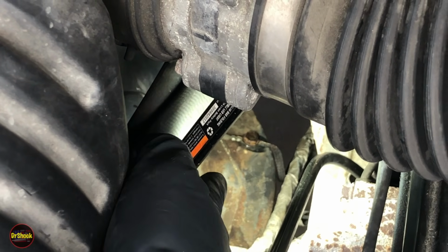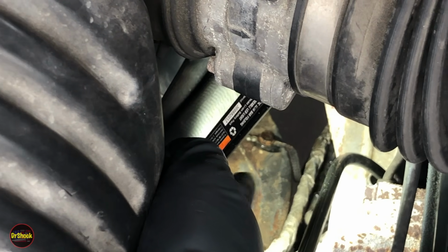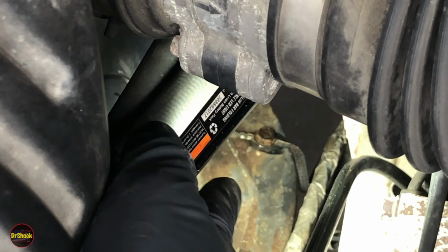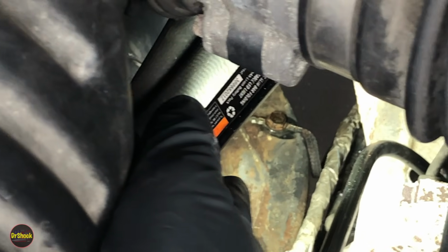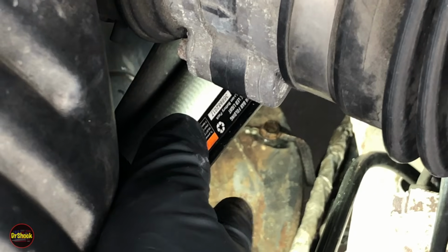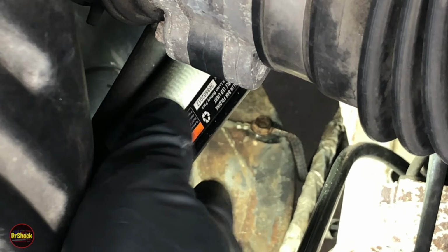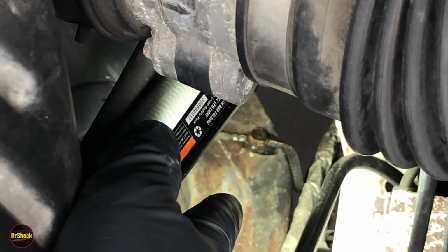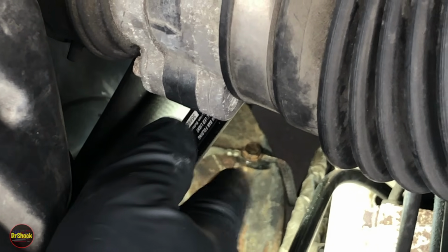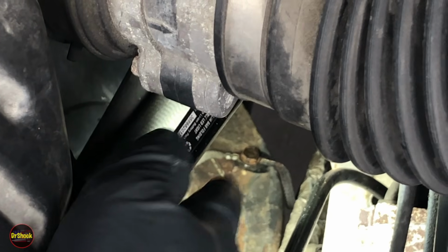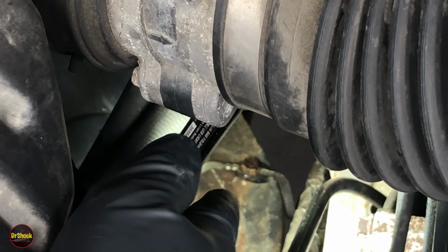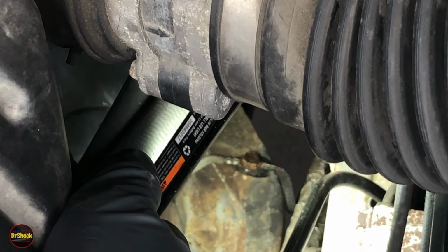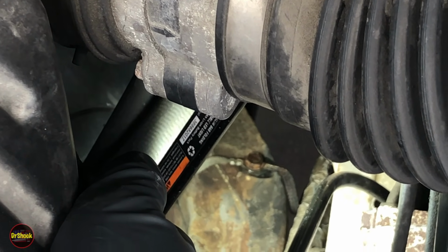All right, guys, after we Cosmoline this, I meant to tell you in the previous clip, you want to also check this strap where it goes up and attaches to the back of the cylinder head. If that ground strap is frayed or broken, you need to replace it as part of doing the due diligence on this ground circuit 150 diagnostic that we're doing. You also want to check the mounting bolt and nut that this attaches to on the back of the cylinder head for the Vortec 50, 57, and for the Diesel 65s that have this mounting point, to make sure that that also does not need to be touched up and sanded.